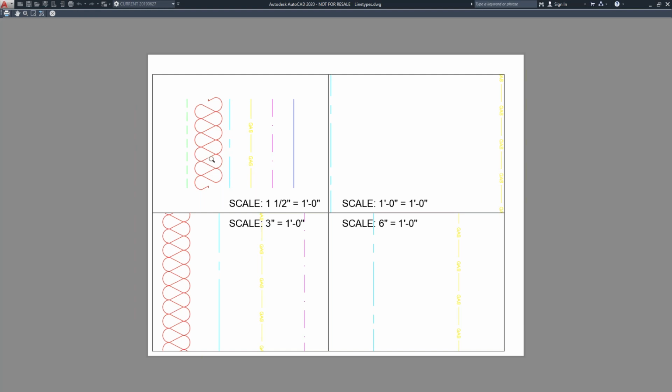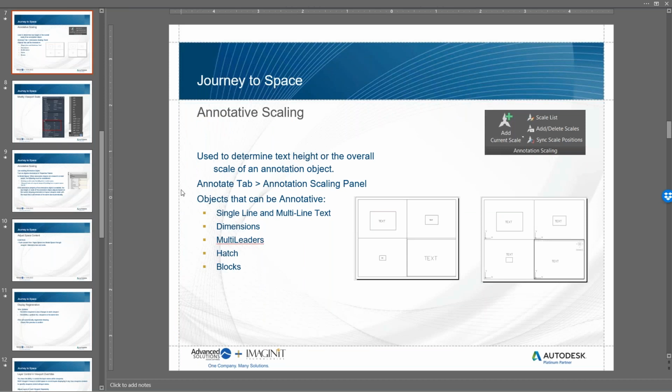So you can see that the batting and gas and other line types are the same relative offset for each of the line work elements regardless of the scale factor. So it will update when you print, so you don't need to be concerned of it accidentally printing incorrectly if you forget to regenerate. Another option is blocks.